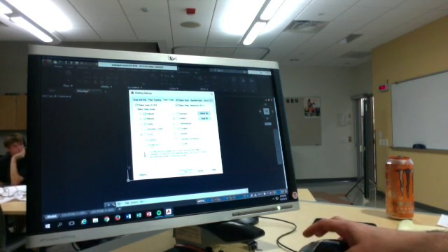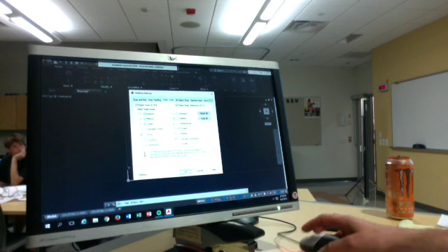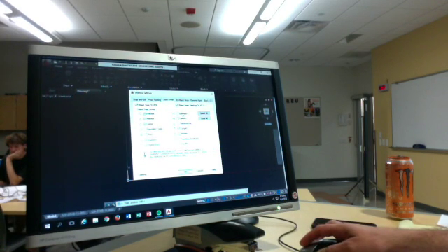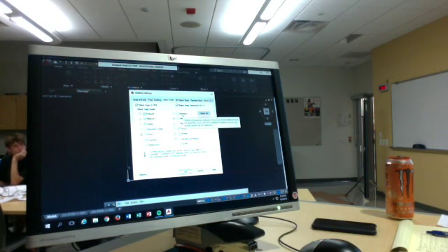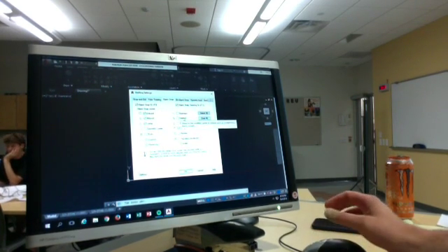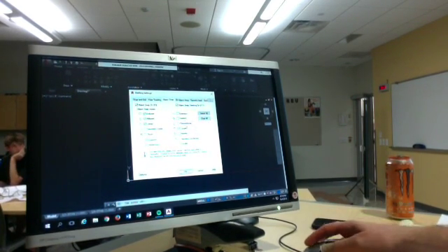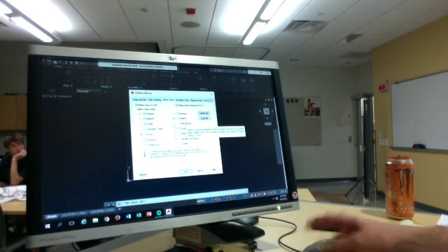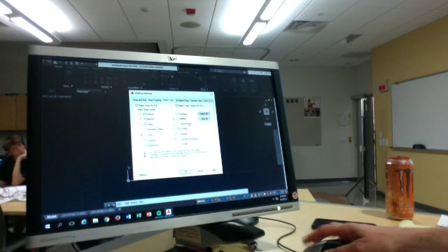Intersection, where two lines cross over each other, including polylines and circles, things like that, ellipses. Insertion point, that's for if you're using a block. We'll talk about blocks later. Perpendicular, that one's good for what I do. You can take it or leave it.